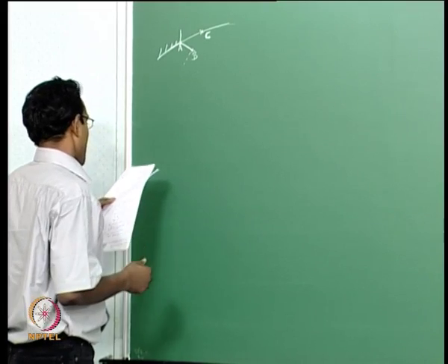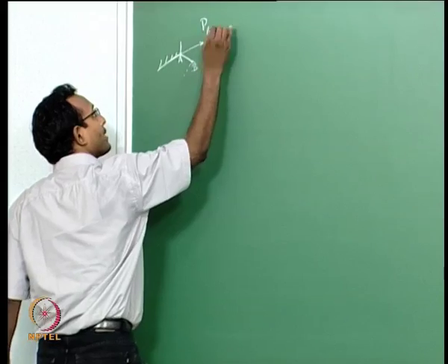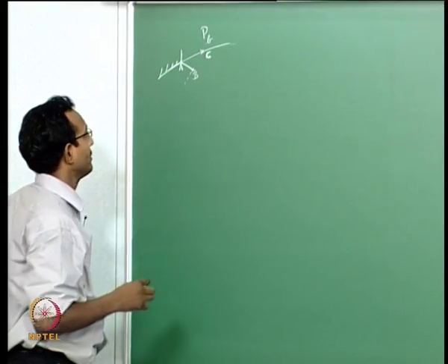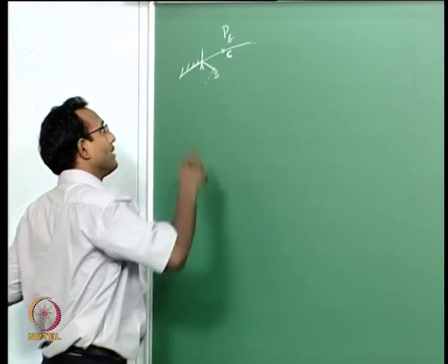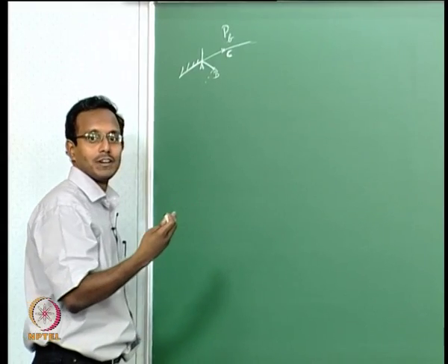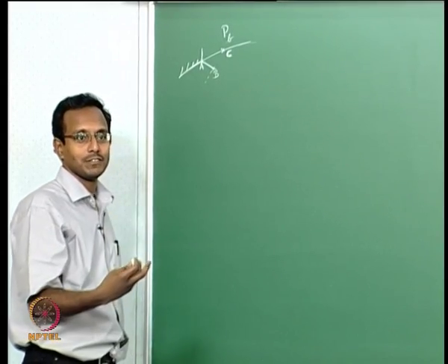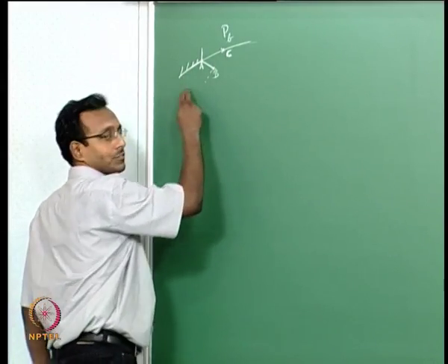And what is given? Since it is a pressure boundary, I know my exit pressure, the back pressure there, that is given, and now I just have to go and find these points. How will I find them? I already told you the answer in some way. Mach number is decided by the pressure. I already know my P naught in this region.